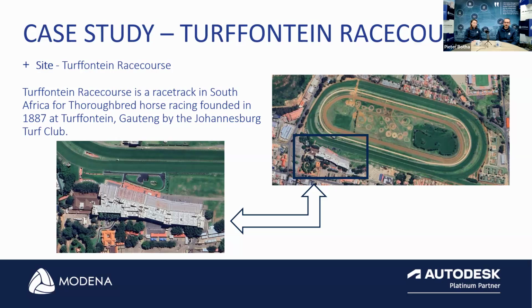I see that we have a question regarding the in-ceiling scanning. When we move into the more engineering space, plant space and so forth, condensed and highly populated with equipment, that complicates things a little bit, in the sense that we need to do more scans to capture all the angles of that space. With that, depending on the complexity, we can cover about 1,000 to 2,000 square meters in a day. Those are some good numbers just to give you an indication of what we're looking at. Do we want to take this question?